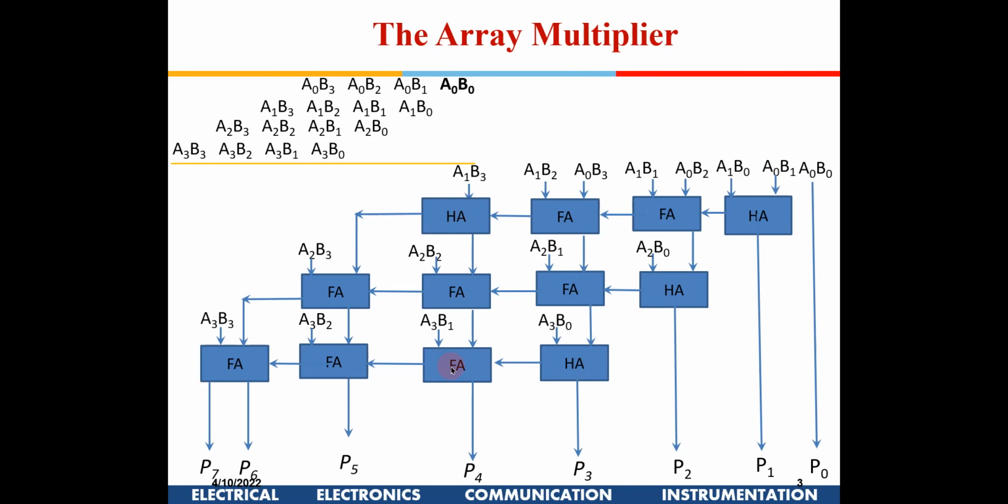Lastly you can have a half adder here, you put a full adder here, and you take A3 B3 to the top. Okay, so that also can be done. But essentially this will remain one half adder and two full adders in this vertical chain. At least that much will be required. So you get one more partial product, and then here there are 2 bits to be added, and carry from here also. This carry needs to be catered for. So all these carries, you just keep expanding it till you get the total partial products.